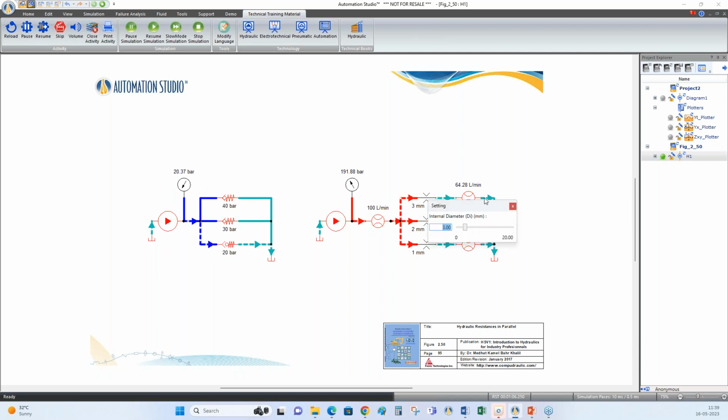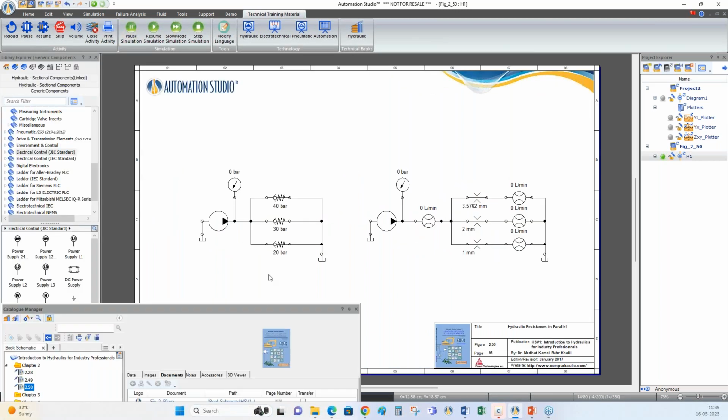If I completely open this orifice, for example, you can see since there is no restriction, the pressure at this point is only 0.75 bar. So like that, different scenarios can be taught using the already presented inbuilt circuits in this technical book section.